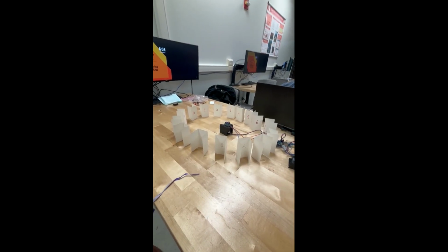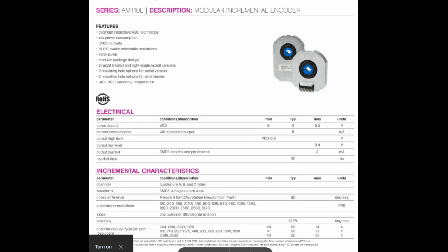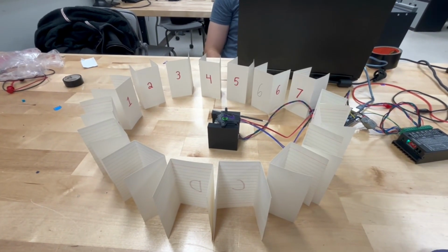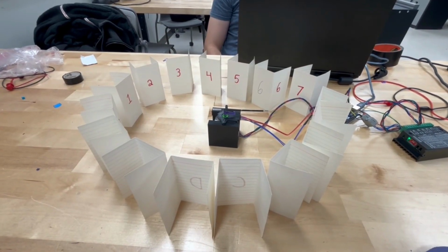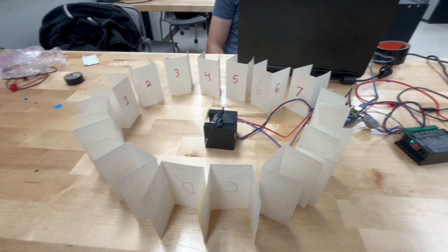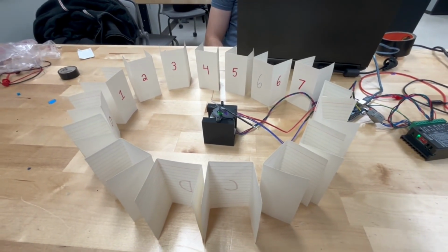In the selected rotary encoder, the position, speed, and direction are determined by two signals being measured, channel A and channel B. These channels measure capacitance as conductive portions of the disk pass by them. The speed is determined by how many pulses pass by in a specified duration of time. Position is determined by counting how many pulses have occurred and multiplying that by the distance covered in one pulse. The direction is calculated by analyzing if the A signal leads or lags behind the B signal. Additionally, there is a signal Z that tracks full revolutions.